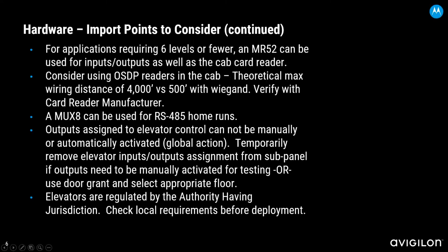There we go. So also something to configure or consider, and Francisco mentioned this on Monday when he talked about OSDP. OSDP readers are a great solution for elevator cabs, especially if you're in a high-rise facility where the cable distance is going to exceed 500 feet.